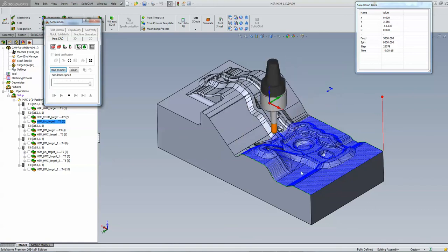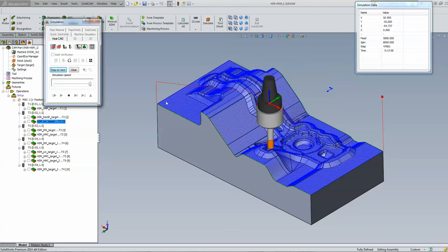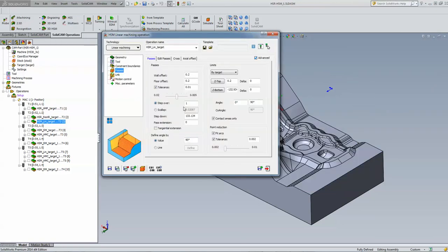Now this is every millimeter, but it's also staying away from the surface. It's not exactly on the surface itself. Let me actually show this to you as well. We stayed 0.2 millimeters away. Notice we went a little further in, but not close enough yet.